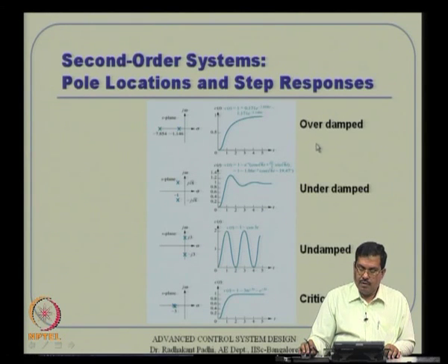Okay. Now, moving further, depending on the pole locations, we will have different response characteristics. Here the pole location is real but non-repeated. Then there will not be any oscillation, so the response will go towards a steady value like that. Suppose the poles are complex conjugate pairs, then it is the classic case of an underdamped system, so it will have this response characteristic.